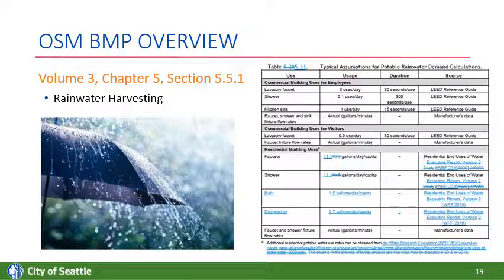If rainwater harvesting is selected for category 4, the on-site list, the rainwater harvesting system shall reduce discharge of rooftop runoff by 25% on an average annual basis as determined by an approved continuous simulation model. So the category 4 on-site list approach requires that modeling to be provided in order to use that BMP.